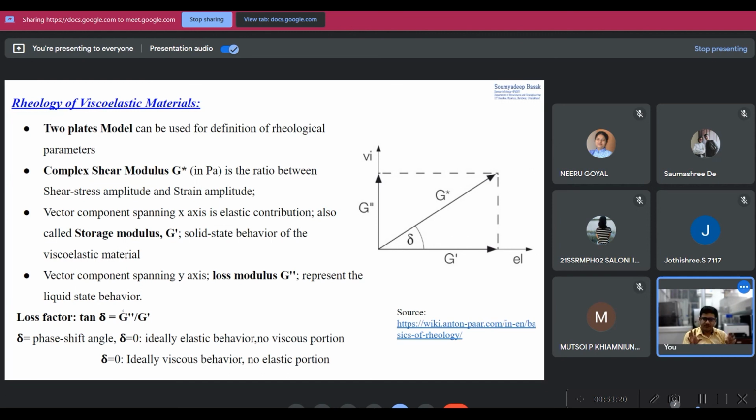Okay, so viscoelastic polymers show this kind of properties, and we measure this G prime and G double prime, the storage modulus and loss modulus. If you read the hydrogel papers, you can see these measurements using the DMA, dynamic mechanical analyzer. They study how this G prime and G double prime change depending upon the polymer's characteristic.